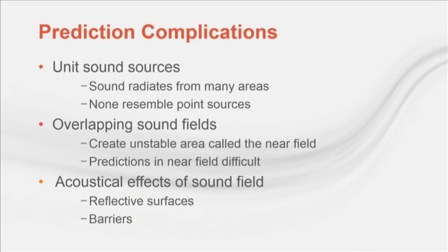Reflective surfaces behind or beside the sound source redirect sound toward the receiver location. But reflective surfaces between the source and the receiver, also called barriers, tend to block the sound and result in lower sound at the receiver. Even thermal gradients and atmospheric absorption can affect the sound, but these are generally ignored for distances less than 500 feet. So accurate sound data is important, but even when the sound data quality is good, it may not match the sound produced by an operating unit. And the distance correction equation only works in a simplified scenario.